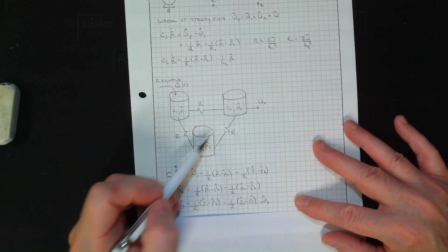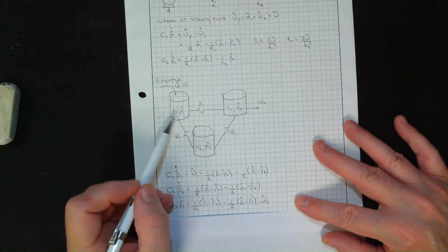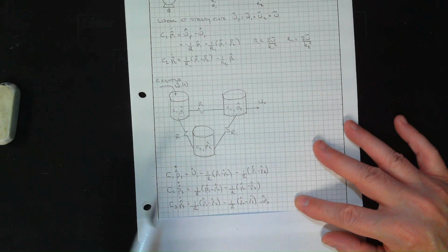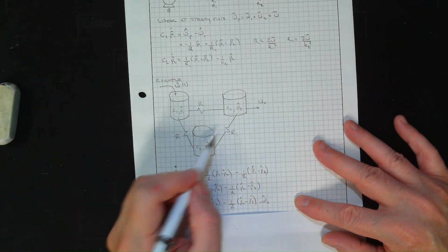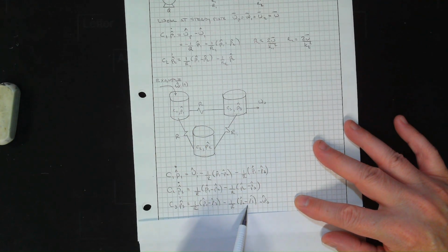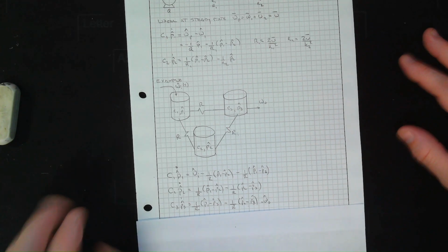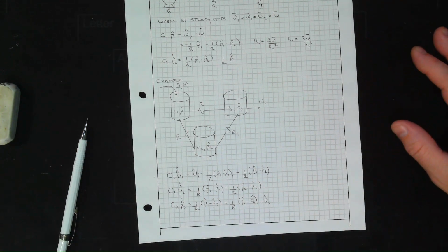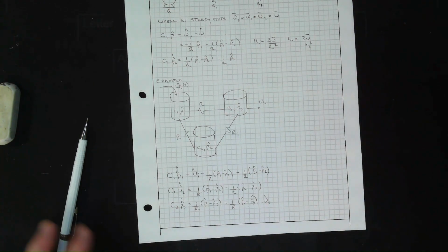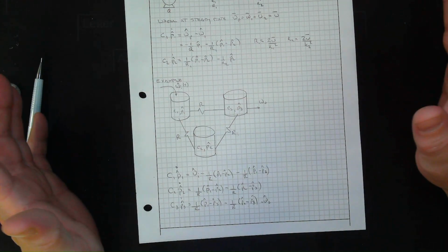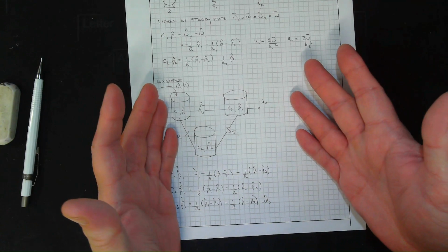Now we'll go to the final tank. We're assuming everything's coming in. So the flow in would be 1 over R, P1 minus P3 hats, and 1 over R, P2 minus P3 hat. Make that easier to see. And then this is the one leaving, minus omega output hat. All done. Easy.